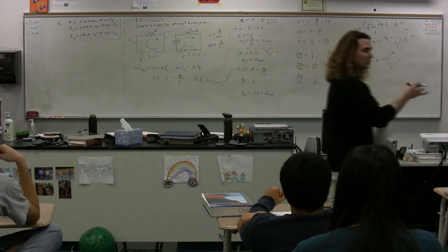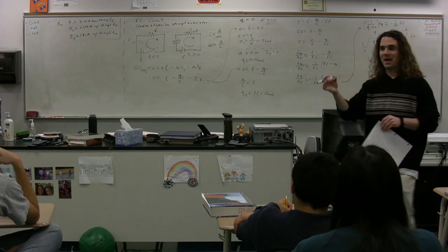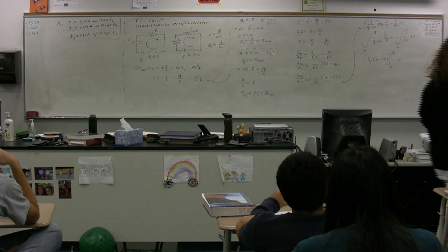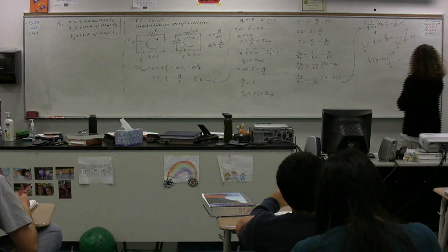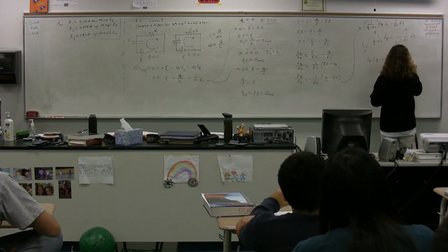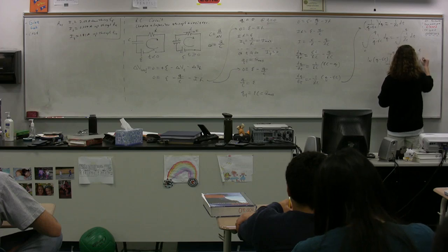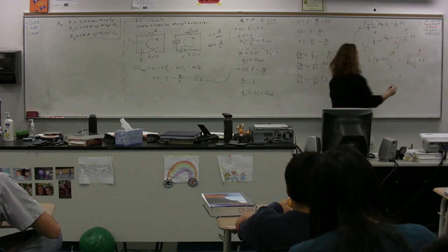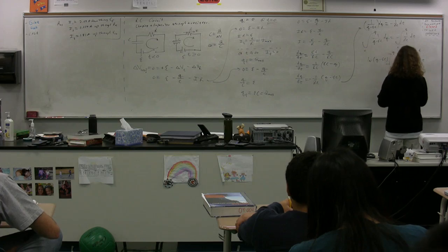Do the resistance R and the capacitance change as a function of time? So those we can just bring out from underneath the integral. I'll do it in 2 steps, but we have negative 1 over RC integral from 0 to t dt. So on the right-hand side, it's just t. So we have negative t over RC.